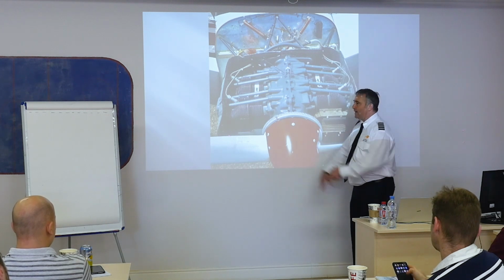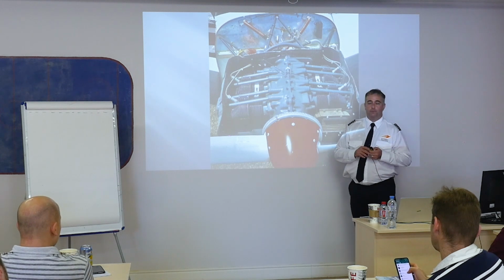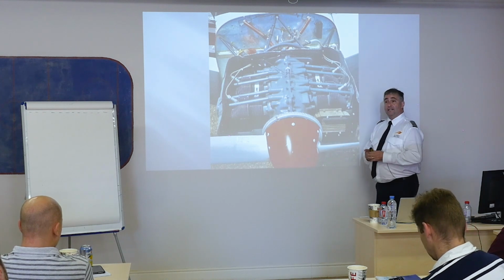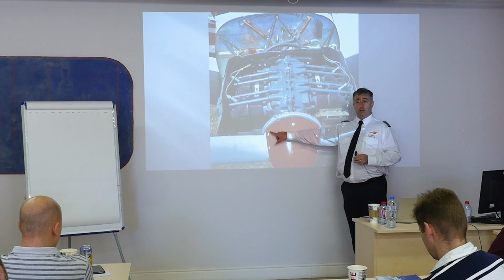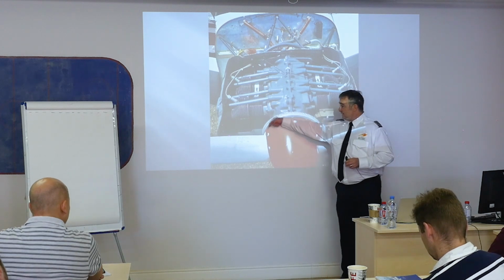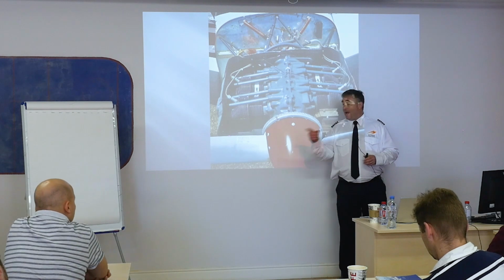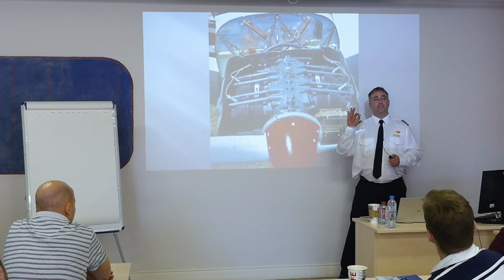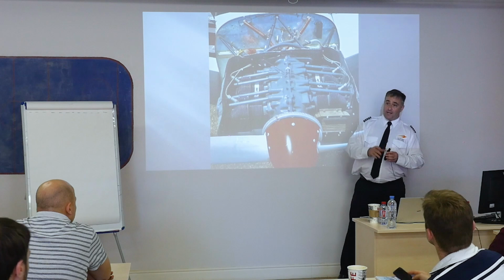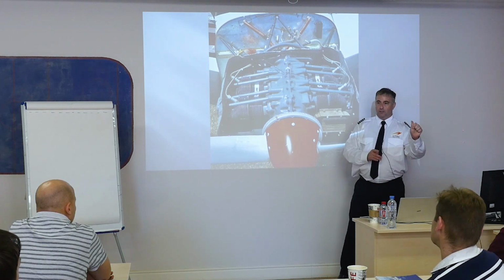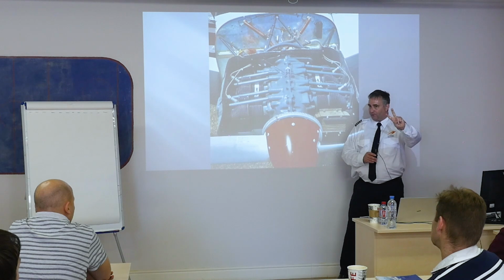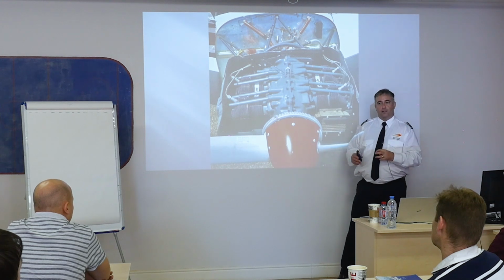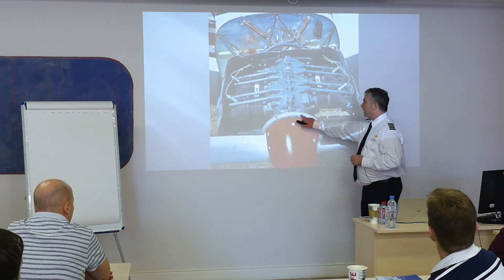A long time ago, you got the guy out there swinging the propeller, doing hand prop. No one's going to do that, ever. Okay? Instead, we'll turn a key, and that key will close the circuit for the starter. The starter will momentarily engage the flywheel and spin rapidly so that the engine can start. What's very important is after the engine starts, like immediately after, you have to release the starter. You don't want to continue to hold that starter because a couple things happen. It's either breaking the starter, or it will slow the engine down so it won't run. Okay? So this is part of the starting mechanism.